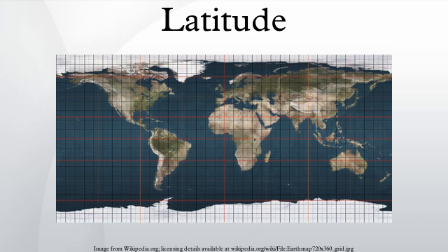The evaluation of the meridian distance integral is central to many studies in geodesy and map projection. It can be evaluated by expanding the integral by the binomial series and integrating term by term. See meridian arc for details. The length of the meridian arc between two given latitudes is given by replacing the limits of the integral by the latitudes concerned. The length of a small meridian arc is given by the following. When the latitude difference is 1 degree, corresponding to π/180 radians, the arc distance is about the following.